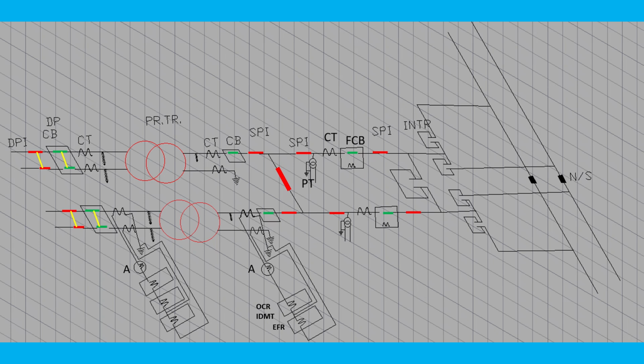It is reducing it for control operation with the 110 volt DC relaying system. So CTPT you must know clearly, and you should also know that in circuit break condition only you can make or break the isolator switches. In circuit break condition, that means when the current is not flowing through the circuit, at that time only you